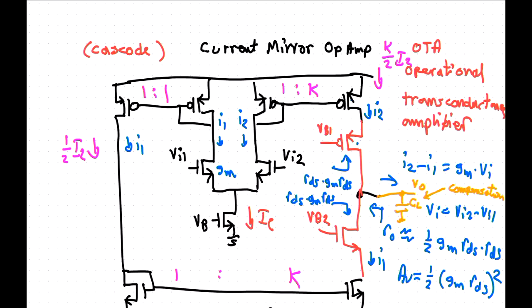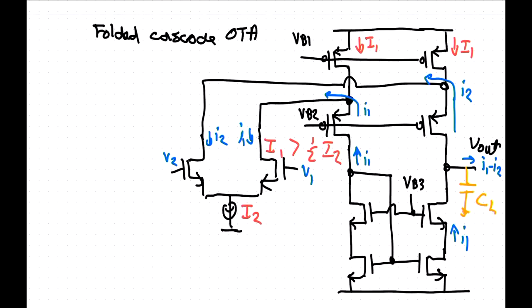So we're really probably sitting about 1 VT shy of the positive supply in how high the common mode can go here. If we look at the folded cascode here, that's not the case, because we can bias this as a wide swing cascode, so the voltage on the drain here is going to be just one effective voltage below the positive supply. So if the threshold voltage is positive, this can go above the positive power supply, easy. So this has a much better common mode in terms of going high than the other one. Going low, they'll be the same.